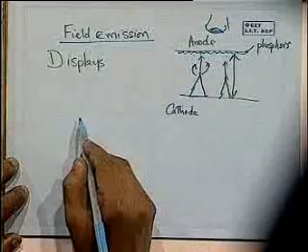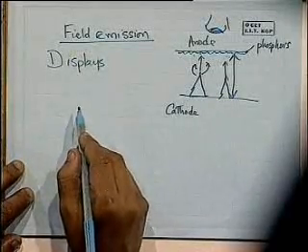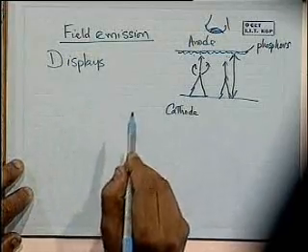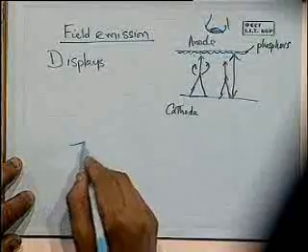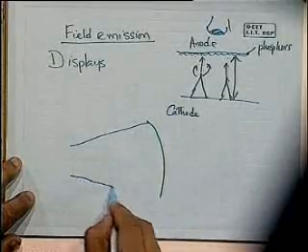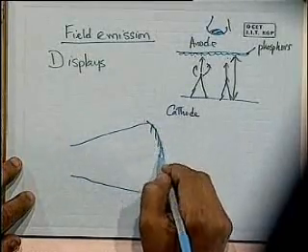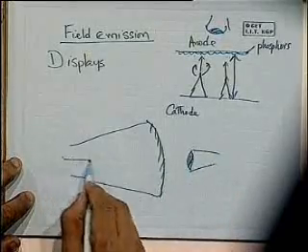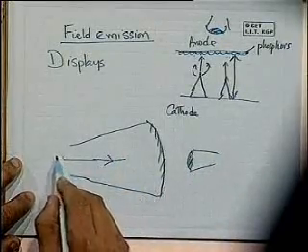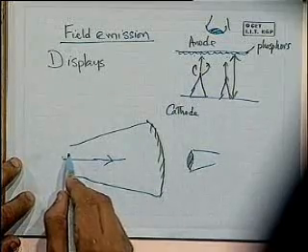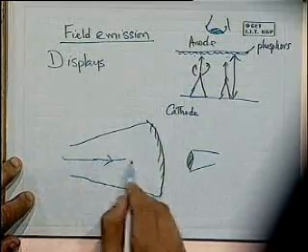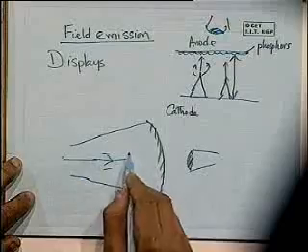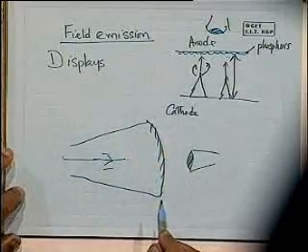So the viewer is on this side, our eye is here, and we are looking at a display where the light is produced by the emission of electrons from here and striking the anode that is coated by phosphors to produce appropriate colored light. Do you see the immediate contrast with the earlier vacuum tube that we looked at? The modern version of it is the monitor, computer screen, and so on. Right? It fundamentally is a cathode ray tube, where we've got coating over here, and we are viewing from this side, and a beam of electrons that is thermionically emitted. We heat up the cathode, and we get a suitable deflection system, and we can create an image here.